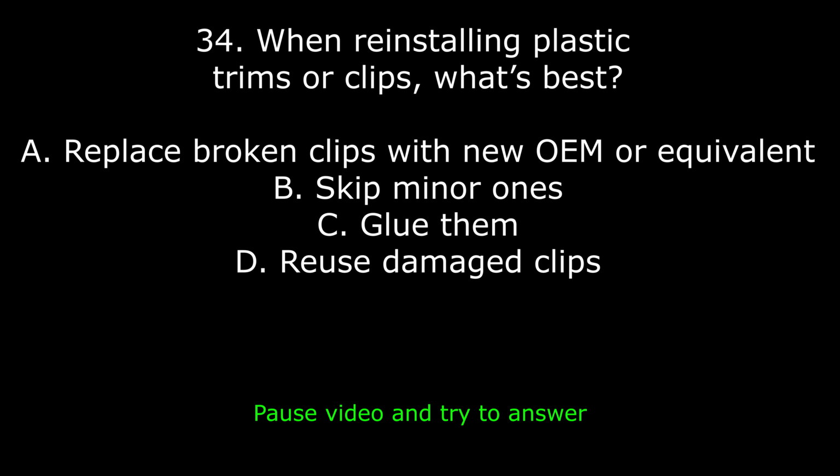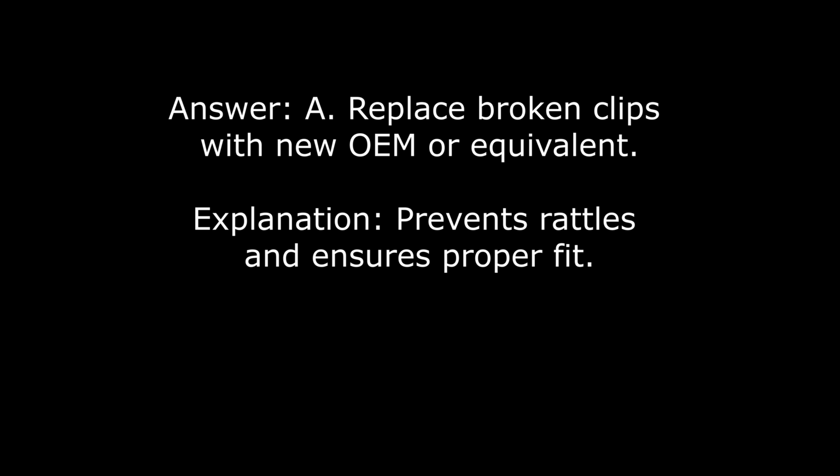34. When reinstalling plastic trims or clips, what's best? A. Replace broken clips with new OEM or equivalent. B. Skip minor ones. C. Glue them. D. Reuse damaged clips. Answer: A. Replace broken clips with new OEM or equivalent. Explanation: prevents rattles and ensures proper fit.